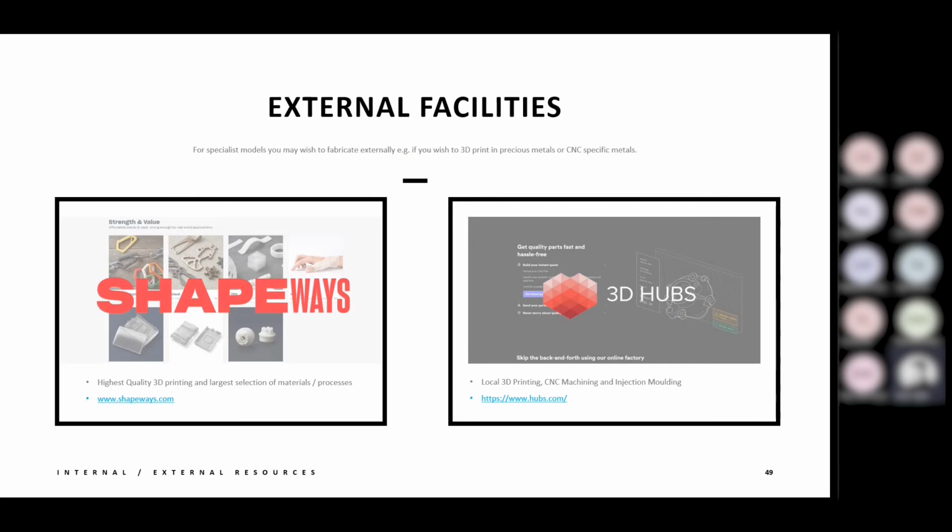But essentially, they have the biggest selection of materials that you can 3D print. So I've printed in platinum, gold, rose gold, just about every plastic you can think of, different resins, and these are all from different scales as well, different levels of detail. And again, they can do this stuff down to like the micron levels of detail, especially for the precious metals, like what we discussed a second ago. Essentially they 3D print those in like a wax material. They then cast those and melt out the wax, and that gives them a mold to work with to pour in the liquid metals. And then they just smash away the mold after, and you're left with the metal piece. Absolutely fantastic process.